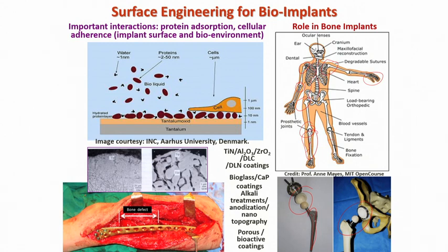Body fluid may cause corrosion and damage and start leaching from this metallic stem, which could be, let's say, titanium or maybe stainless steel or cobalt based alloys or something. But if it is coated with hydroxyapatite, then the body fluid actually doesn't cause any damage, and on top of that there could be natural bone growth or tissue growth on this, and the metallic system can integrate well with your body over a period of time.